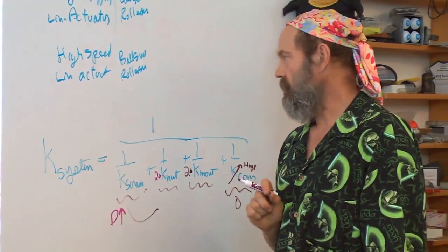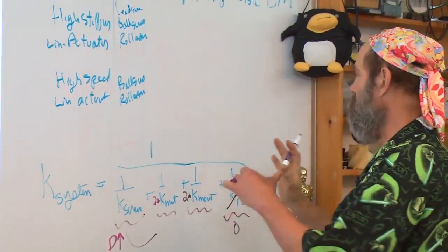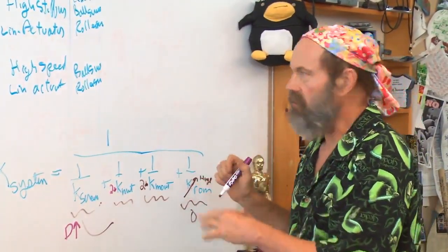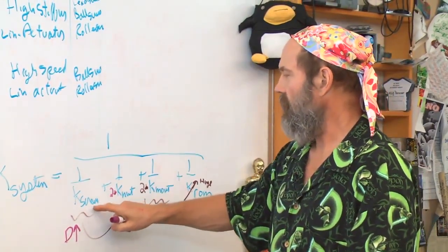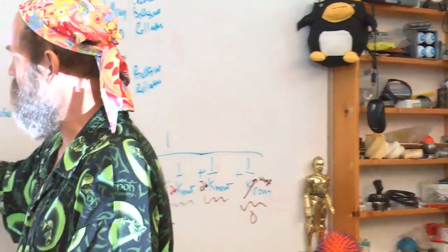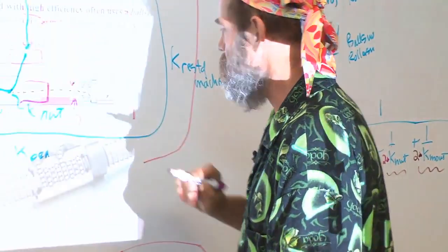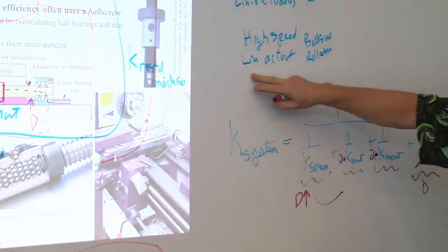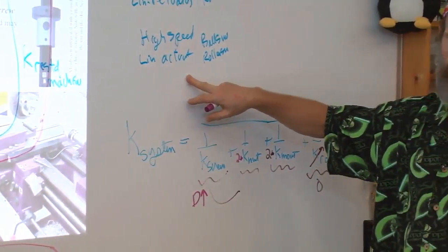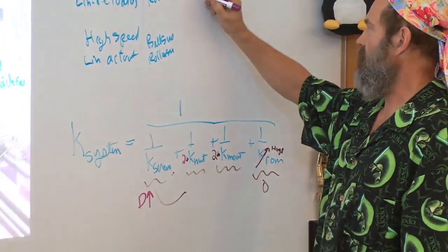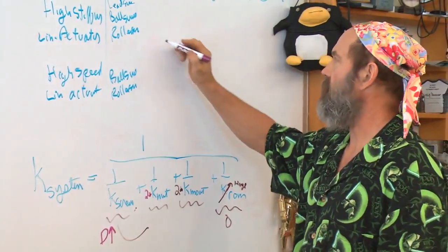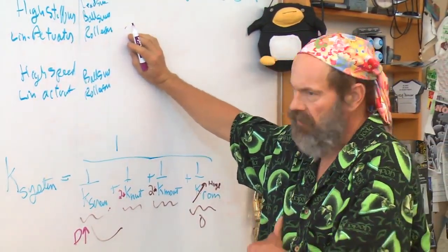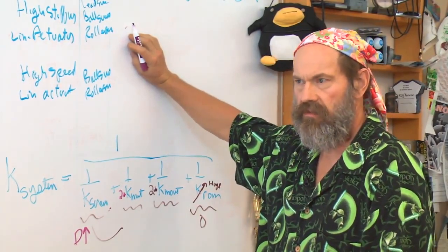And watch what happens. Now remember, this is all in the analysis column, and this is on the early concepting of my machine that I'm doing this type of analysis. So I want to know how the screw shaft stiffness goes with the diameter. I also want to keep in mind my other primary function or requirement of the speed that I want to go. So let's look at this one here. The stiffness of a shaft in compression or tension. What is stiffness? If you don't know exactly and you can't rattle off A over L, think it through.